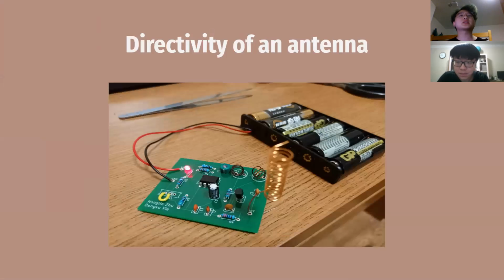So let's move on to the directivity of the antenna. We think the router's antenna is directional. The signal in the direction parallel to the antenna is the strongest, while the signal in other directions is weak. Therefore, the router's antenna will be turned into different directions to maximize the signal range. The number of antennas also affects the signal strength, but because we are designing a circuit that only uses one antenna, and based on the study and research we found so far, an antenna works best when it is straight up. But when we turned the antenna straight up, it didn't work.